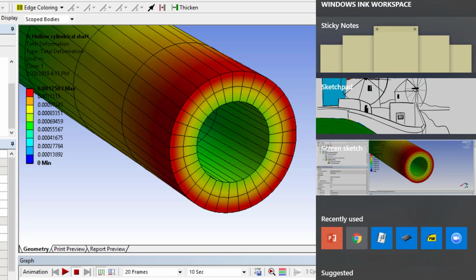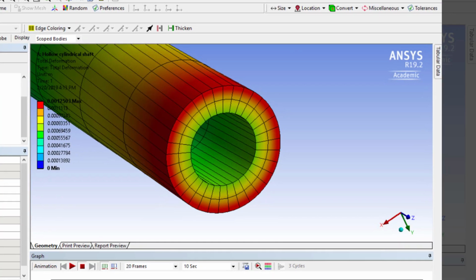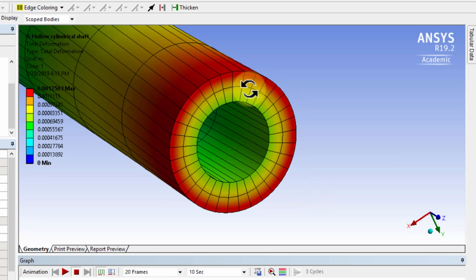each cross-section is just rotating. In that case, a node over here, if it's just moving over here, and a node over here is just moving over here, they should have the same displacement if they have the same rotation. And then I would expect that the node over here would move more because it's farther away from the center. So the trend within the cross-section is also consistent with rigid body rotation.